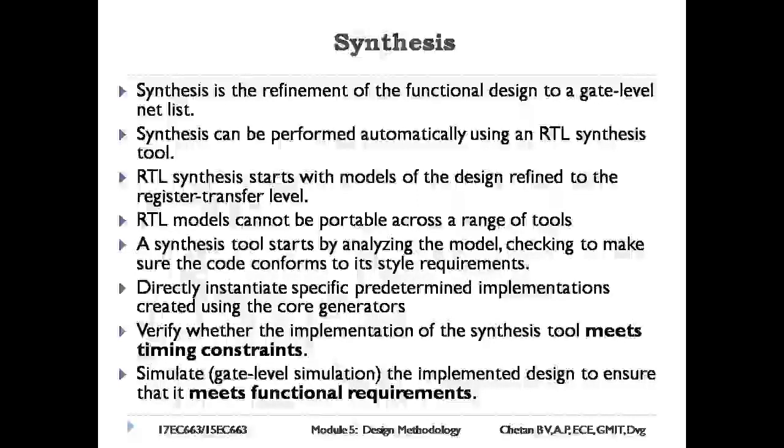A synthesis tool starts by analyzing the model, checking to make sure the code conforms to its style requirements. It also performs some design rule checks such as checking for unconnected outputs, undriven inputs, and multiple drivers on non-resolved signals. The tool then infers hardware constructs for the model.